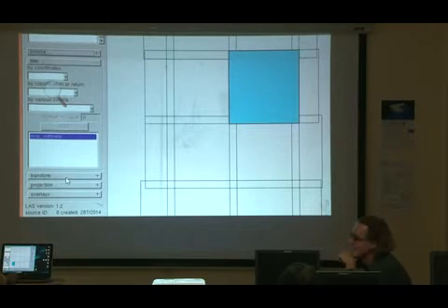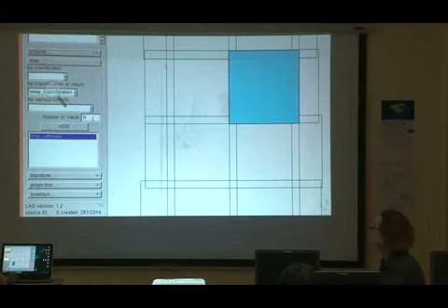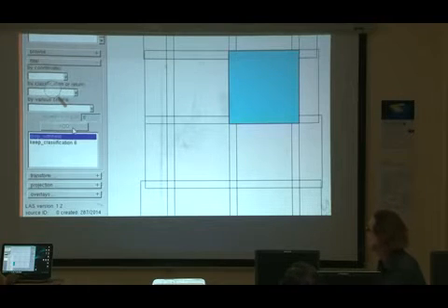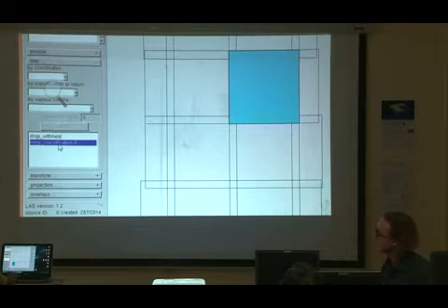The other filter is, I'm looking for the building points, so I want to use only the building points for this. So, keep classification 6. 6 is the building classification. Why? Because we all live in boxes, and boxes have 6 sides. Just another way to remember. So this means drop all the buffers, and from all the points that are not in the buffers, keep only the points which are building points.